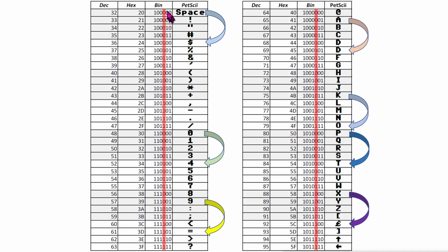And if we analyze this bit further down here, we can see that that is actually the difference of all of these characters that are shifted. So we can conclude that the third bit, or bit 2 as it's called since we start on 0, is actually causing this fault, and it seems like this bit is stuck on 1 and will show a 1 in each case.